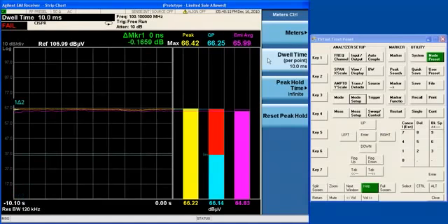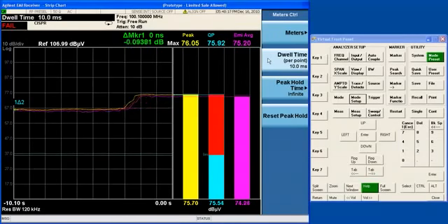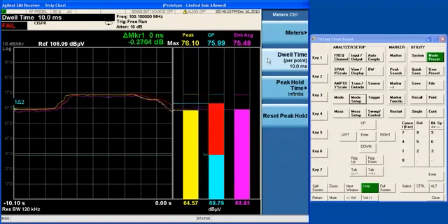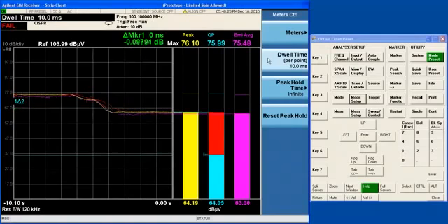And the answer to that question is, well, obviously, the quasi-peak detector responds with some lag to events in the time domain, and of course, if you're trying to make a CISPR compliant measurement of the quasi-peak detector, then you'll want to dwell for a second for sure.